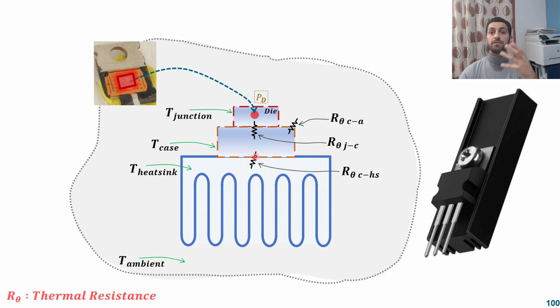this will increase the surface area that can really radiate the heat, and that will make this resistance very, very low, and the temperature developed in the case will also go and be dissipated by the heatsink, because the heatsink now will start acquiring this heat and raise its temperature, and above its fins here, will dissipate it to the ambient. So this is actually what we have. And maybe the last point here, we have another resistance, which is from the heatsink to the ambient, okay?